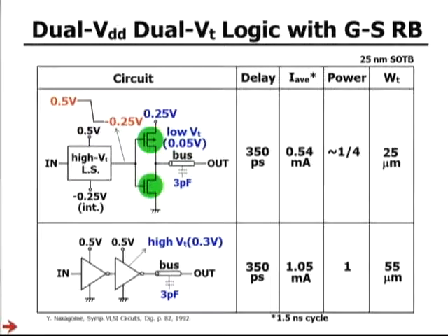To achieve low power and high speed, the input of inverter is overdriven at 0.75 volt by the level shifter. For example, when PMOS is on, the speed is enhanced due to the negative gate voltage of minus 0.5 volts.